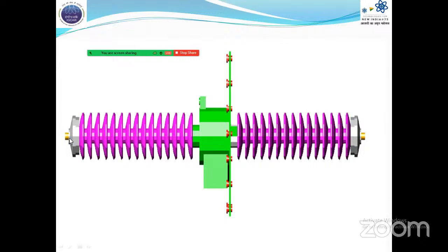So this portion is connected to the indoor switchyard of MAPS to tap the power supply, and this portion is connected to the transformer terminals. So the conductor has to pass through the conducting portion of the wall supporting plate. So this is a conducting portion. Through this, it has to be taken out. This is the general drawing of wall bushing. This is CT.